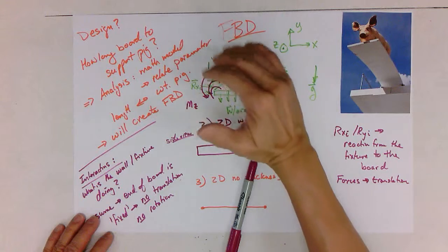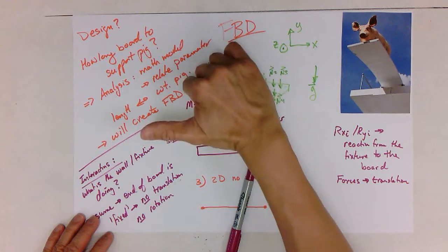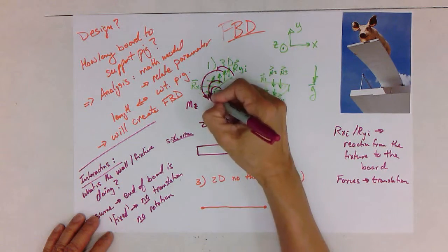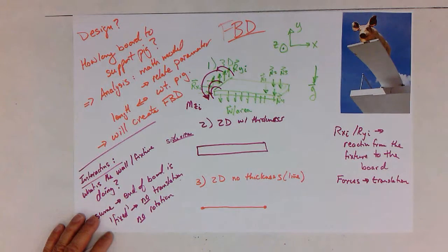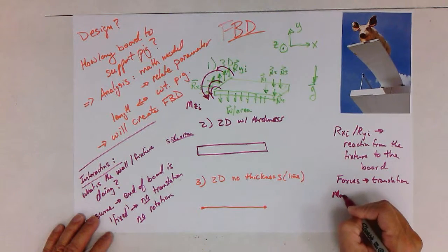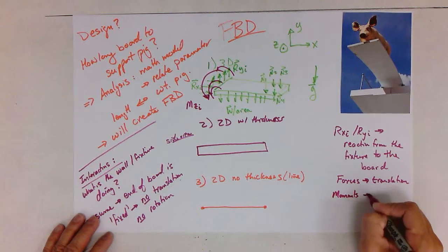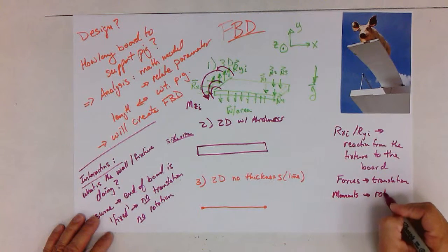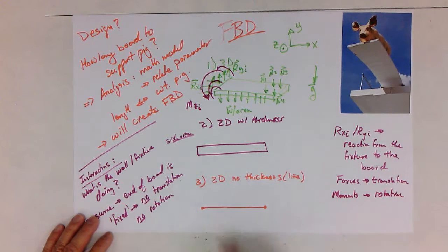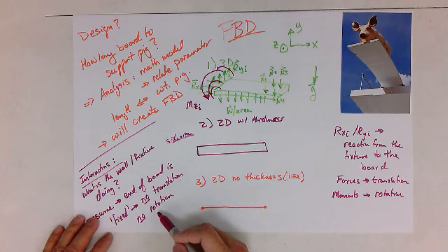These arrows are curving around the axis, which is around the Z-axis. So the moments are coming out of the page, and we have a series of those. So moments prevent or cause rotation. So we've specified no translation, no rotation. We have forces to constrain the motion, displacement, and we have moments to constrain the rotation.